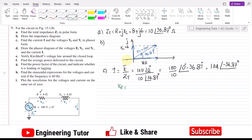As this is a series circuit, the same current flows through both of these elements, and that current is I. So I multiplied by R: the value of I is 10, and the angle it has is minus 36.87 degrees, multiplying it with the value of R, which is 8. So that would be 80, and the angle it has is minus 36.87 degrees. Okay, so that is in volts. This is VR.